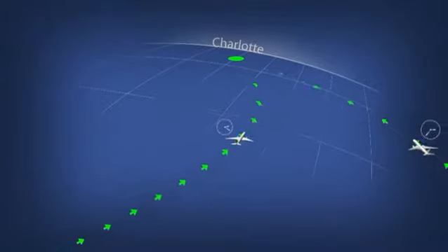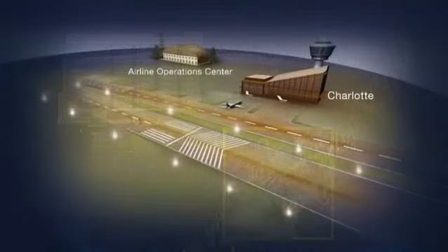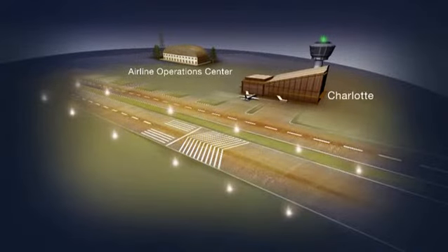As the flights converge on Charlotte, Flight Data Object provides FAA and airline systems with predicted arrival times. With this data, optimal runway assignments, taxi routes, and gate availability are calculated and planned. Conformance monitoring signals pilots along the proper trajectory to the correct runway and taxi route. As the aircraft arrive at the proper gates, the Surface Flight Data Object updates FAA and airline systems to indicate